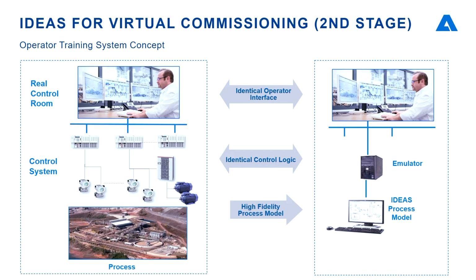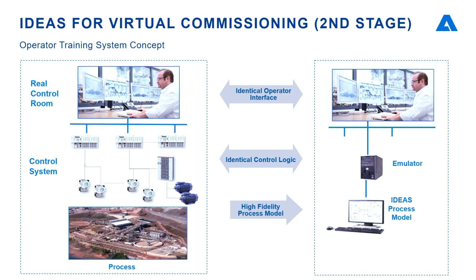Now, here's the interesting part. When we validate the design, it comes to the time when we are getting near commissioning. Imagine around 8 months before the commissioning time. That's when the control system is ready and the design is ready. Instead of going to the site and commissioning the plant one by one, like in the old days, where you find all the problems in the control strategy during commissioning, we are able to do a complete virtual commissioning 8 to 9 months before the actual commissioning time.